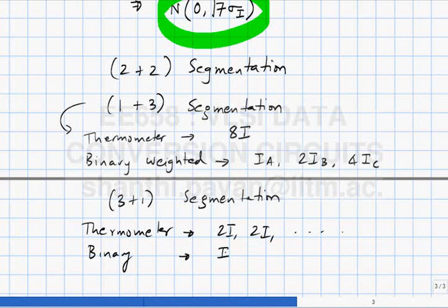Decoder complexity is now 2x the 2+2 implementation, because there you need to take 2 lines and generate 4 lines. Here you take 3 lines and generate 8 lines. Okay.